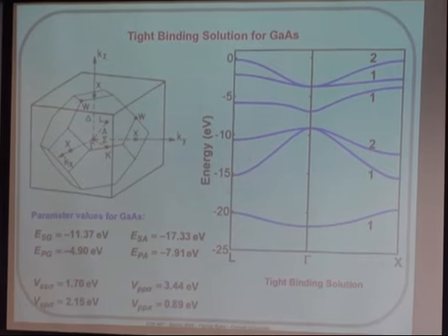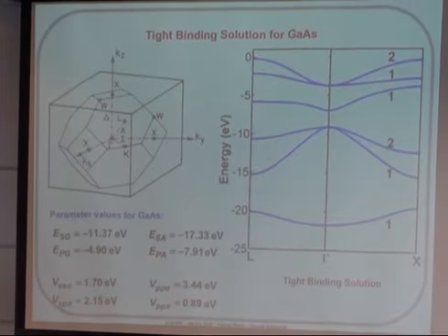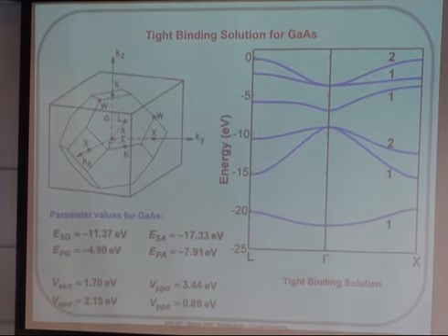You can do that. One of the things I wanted to say, though I don't have much time, is something we'll finish discussing in the next class. One very important thing that comes out of this is you have these energies, so you can plug them in and find all this stuff. For gallium arsenide, you have 8 electrons for two atoms, 4 electrons per atom, and then you have this band filled, that band filled, and that band filled. That band has 2, so 2 plus 1 plus 1 is 4, and 4 times 2 each is 8. So these bands are all filled. These are valence bands. That's the conduction band.